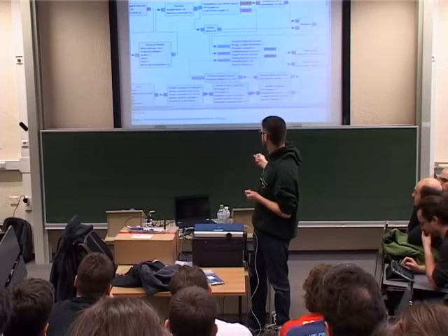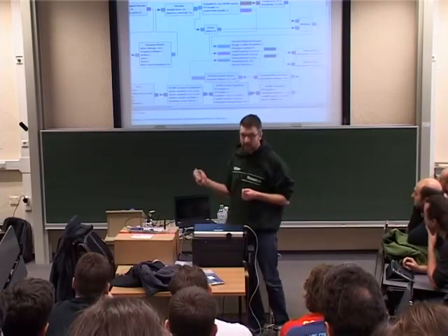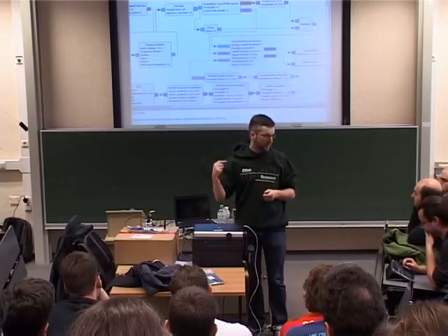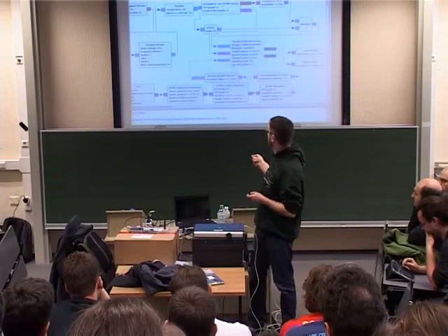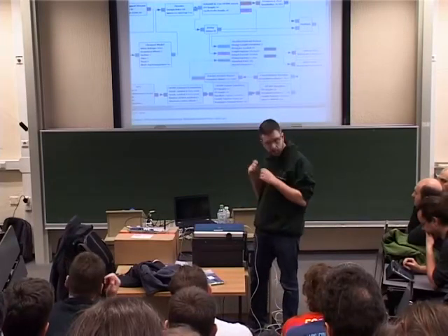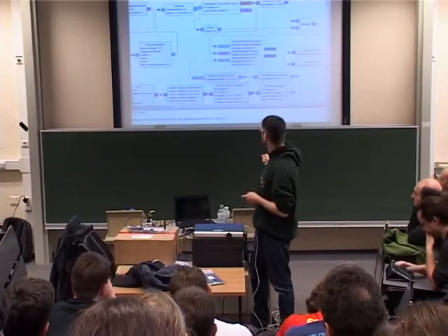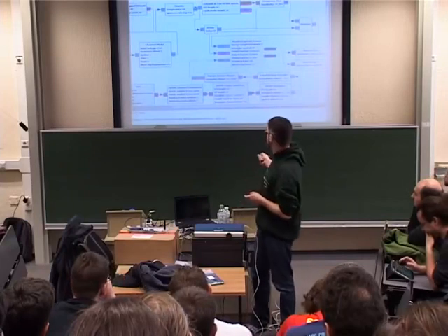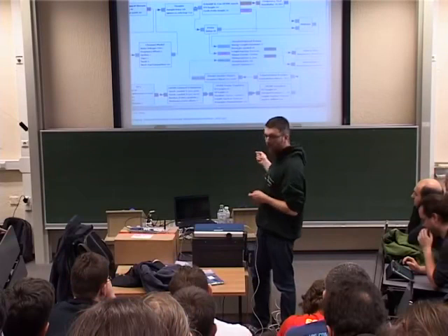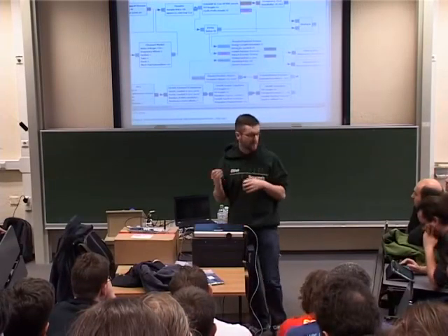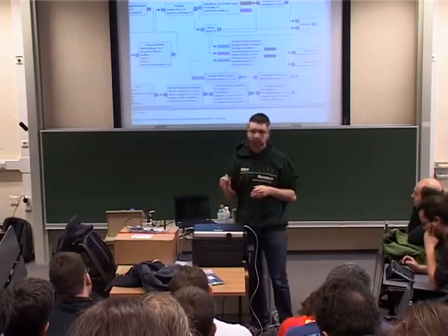This is just a message, okay? If you know what an IIR filter is, it has a feedback loop, and we can't implement these directly in GNU Radio flow graphs. We can put them in blocks, that's fine, but we can't do real feedback loops. But this is different because this block can wait until it receives the message. We can just do it asynchronously. There's no reason to stay within strict timing here.